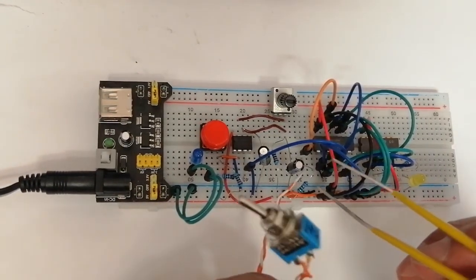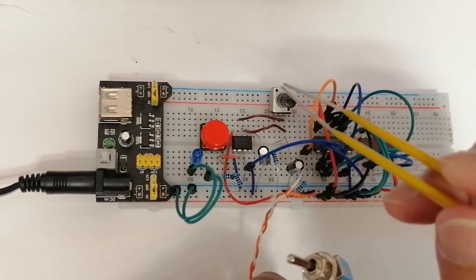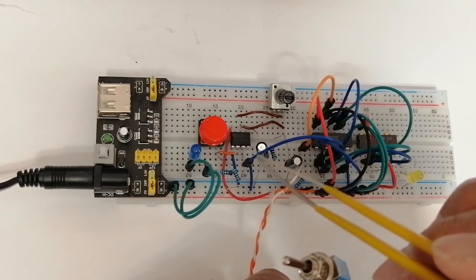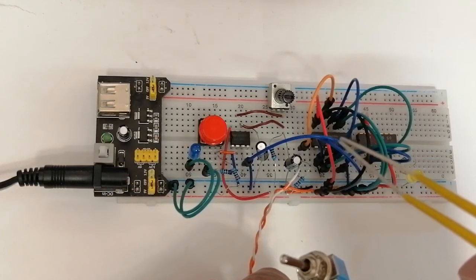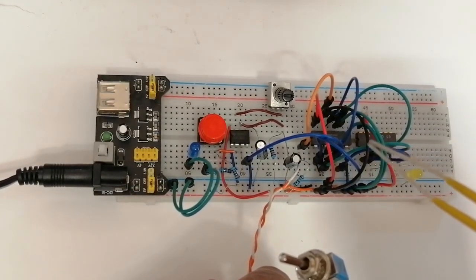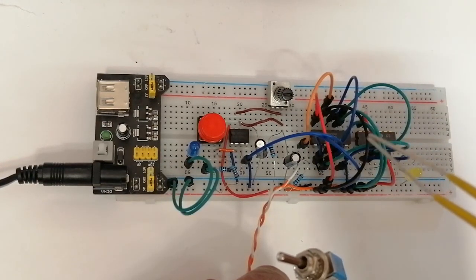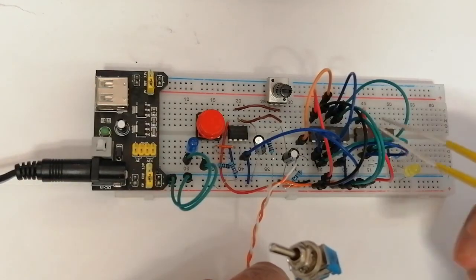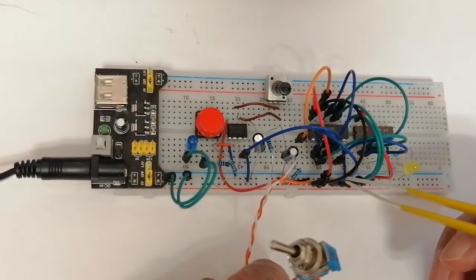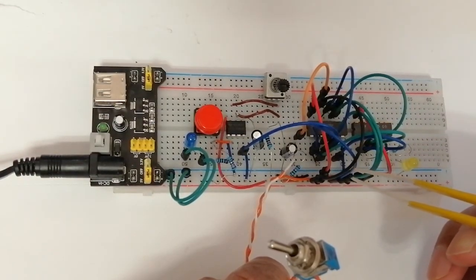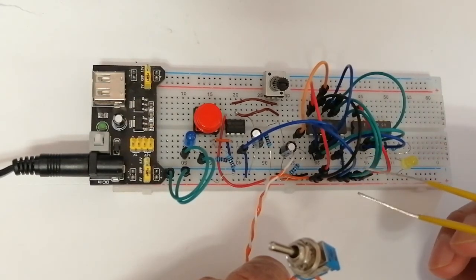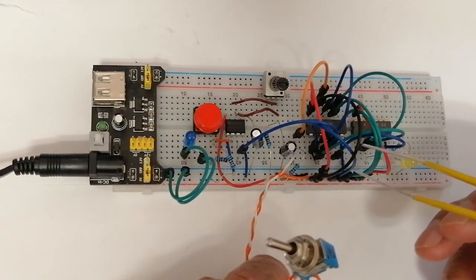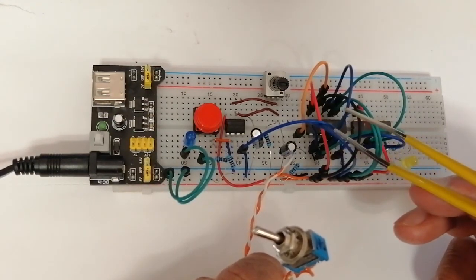Oops, it's a floating switch. This section is from a previous video to generate the single pulse using 555, and this single pulse is used as a clock. This clock goes in here. This is 74LS74 2 flip-flop, and this is 74LS00 NAND gate. And the reason why I got messy is every reset enable line I needed to tie to the high, because digital input, basically if you don't connect anything, it's high, but it's a high impedance input. That means it's like an antenna, and a little noise suddenly gets the pulse and changes the logic state.